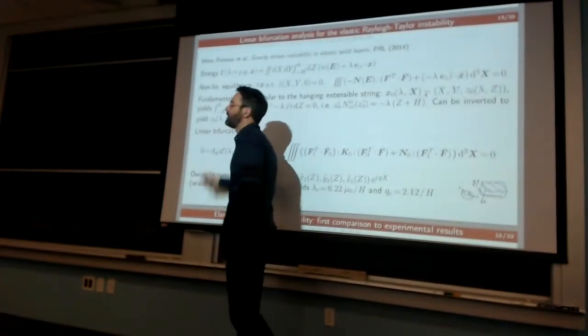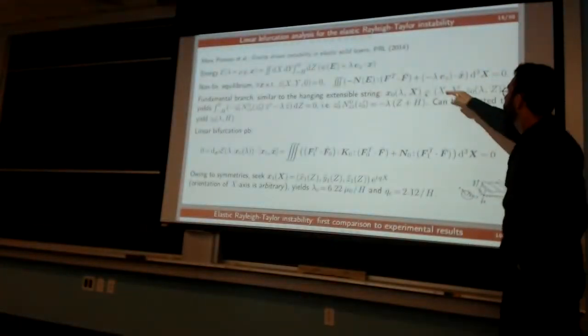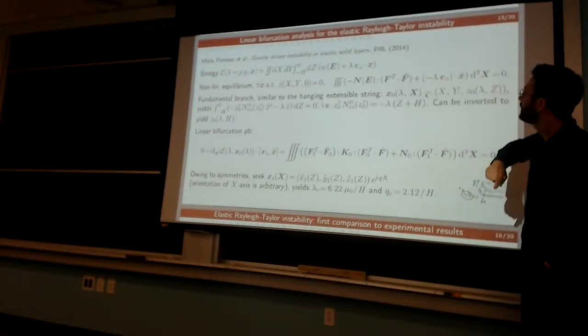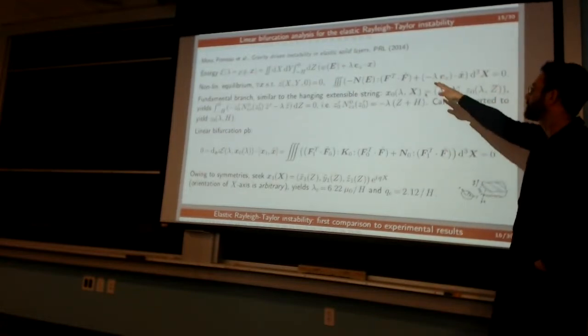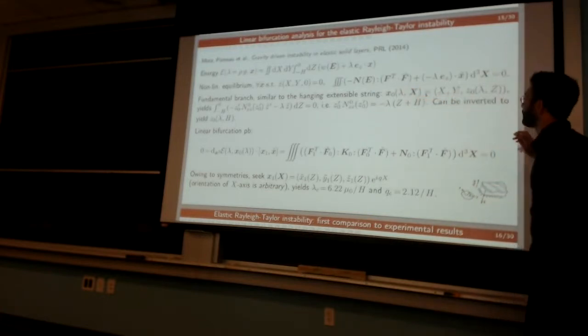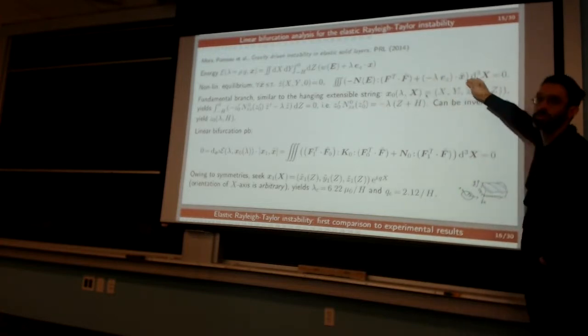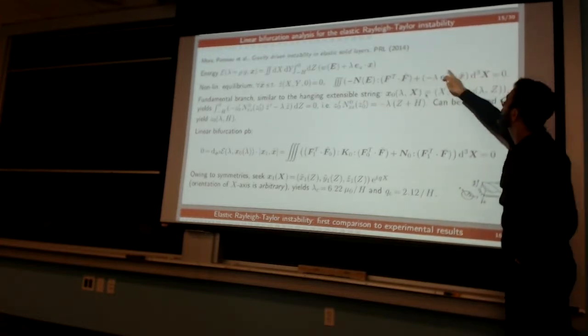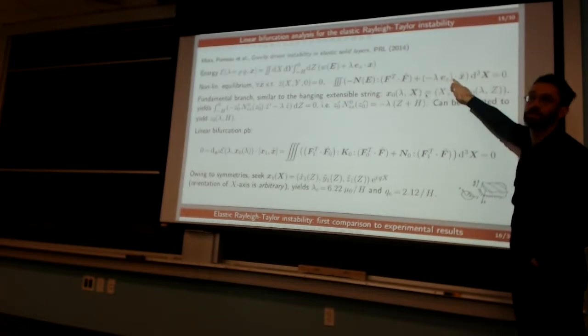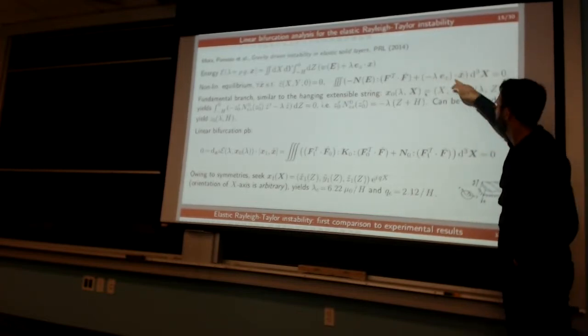Is usually reasonably easy to calculate. Okay, then we can do one more variation here. And very much as in the formula for the stiffness that I was showing at the beginning, we have 3 terms. Well, the simplest one is the one coming from the external potential. This doesn't depend on x. So when you do one more variation, it cancels. So the stiffness from the external potential is just 0.